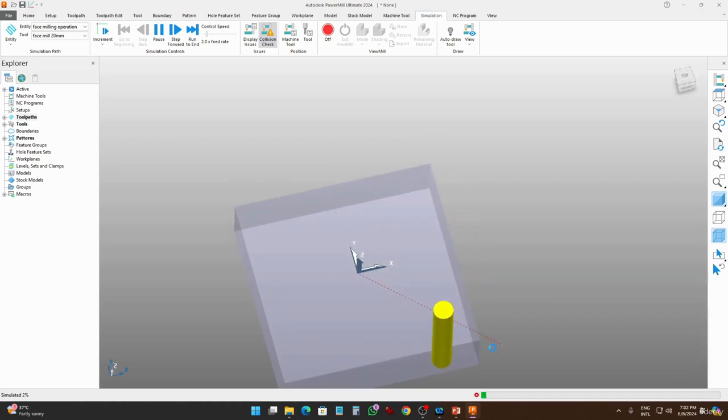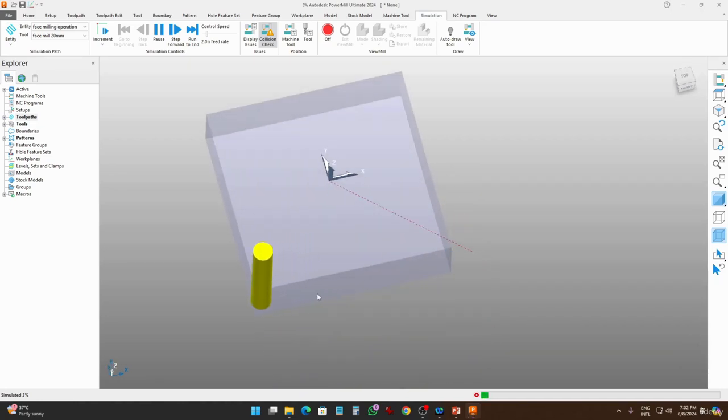So it goes along in the side direction 10 millimeters, and the step direction is 10 millimeters. What you see is that it takes every single step to create the face operation and goes back to its initial position, then takes the next step. So this is what we call a single way operation.